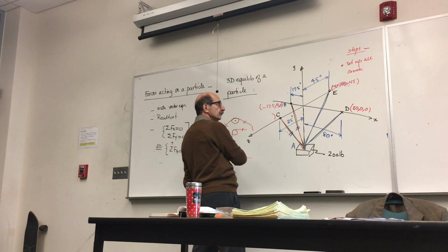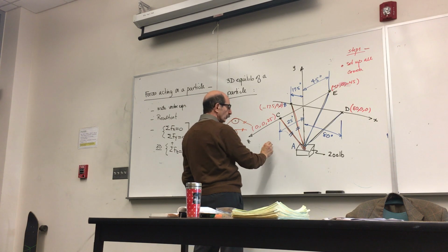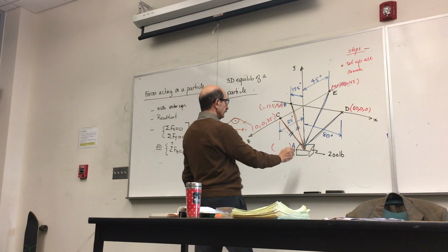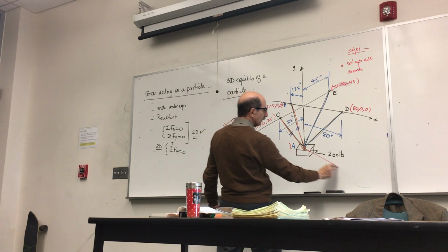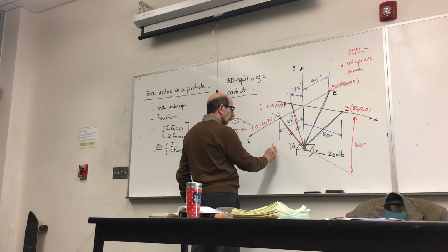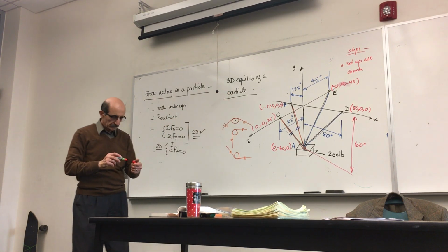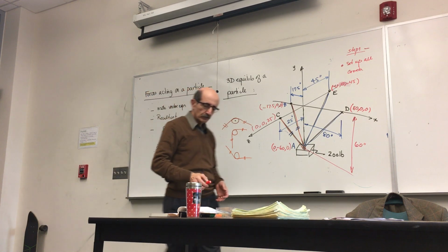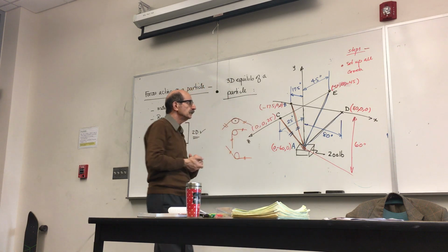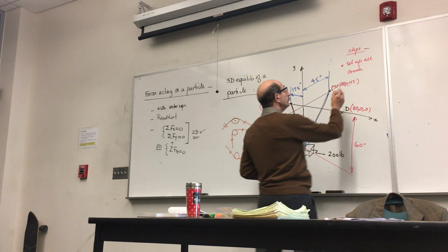Point C is along the z-axis, so it would be 0, 0, 25. And point A is along the negative direction of the y-axis, and this is given, actually I did not write that down, it is given as 60 inches. So it would be 0, negative 60, 0. So that's step one, easy. Easy, yet it helps you save time, because each time you're writing an equation, you don't have to start from scratch to figure out what the coordinate is here. That's all, okay?